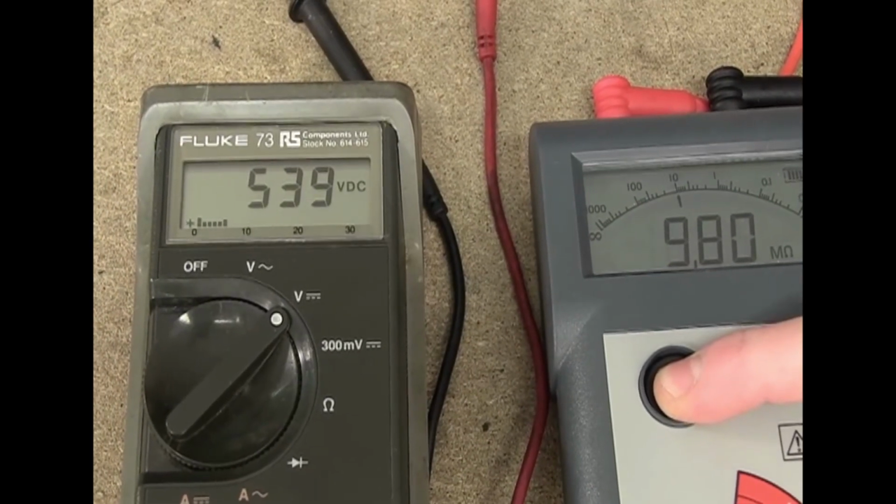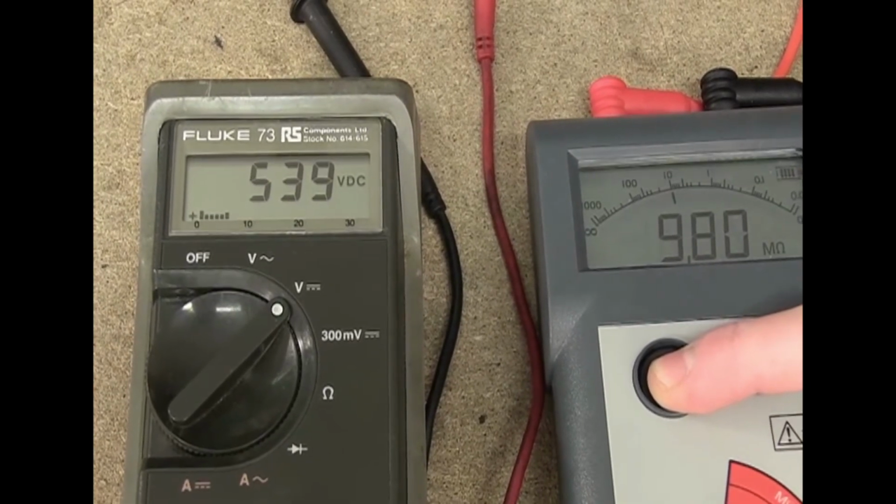Press the black button on the megger and note the readings. Repeat the procedure by interchanging the prongs of the mains cord and note down the readings. What are the observations and results? If there is any reading on the megger, it means that there is some current leaking. The discussion is, this could be due to inadequate insulation of the wiring, which may lead to electric shocks. So, care should be taken to locate the weak spot and immediately ensure adequate insulation.